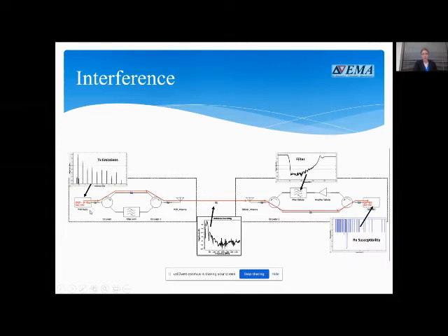But what it shows is that in these kinds of radio systems, you can actually get unpredictable interference because of those multiple frequencies that are bouncing around when you didn't necessarily plan for them. So, for instance, if you're trying to figure out if a particular transmitter will interfere with a particular receiver, you have to consider that the transmitter is not just putting out one frequency. It's putting out one frequency and a bunch of harmonics and some spurious emissions, and it's going through its heterodyne transmitter and then being picked up by the receiver, which again, because of the mixer products and because of additional susceptibilities, additional frequencies the receiver's picking up, can be susceptible not just to the frequency it's designed to pick up, but also to a number of others.